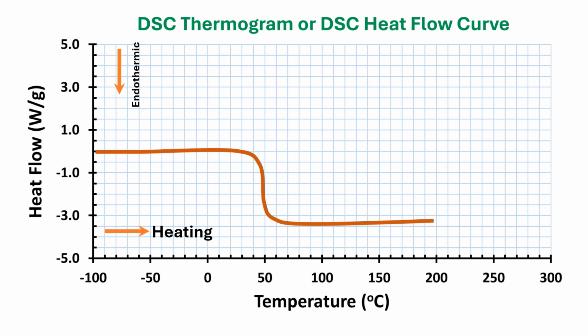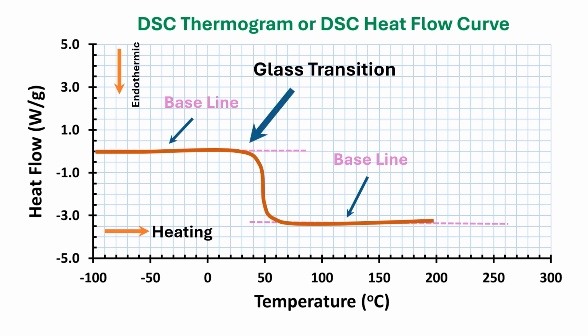If a sudden change in the specific heat occurs in the sample, then we will have a shift in the baseline, and a specific heat before and after remains nearly constant over temperature. The most common example is the glass transition. The glass transition is a second order transition since there is no latent heat involved and only a change of a specific heat occurs.